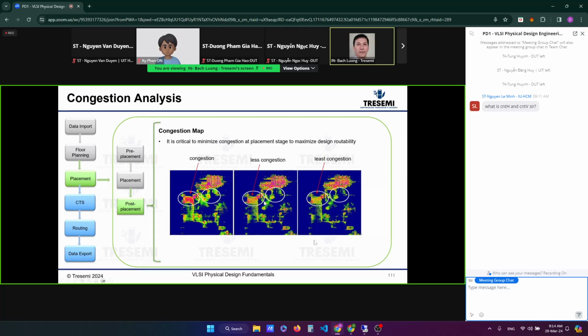Based on the default colors, they go from green to red. Red is very severe, and green is less congestion. You can see the same area has gone down. That gives you a feel of how to read the congestion map: the highlighted red is a severe area, and these are less severe, meaning maybe 1 or 2 tracks short, versus this maybe 5 or 6 tracks short, meaning you need 5 or 6 tracks to finish.